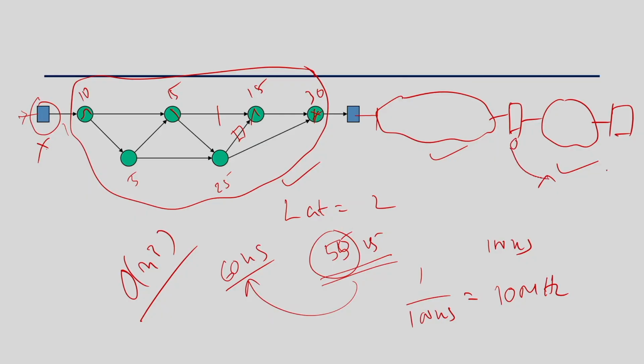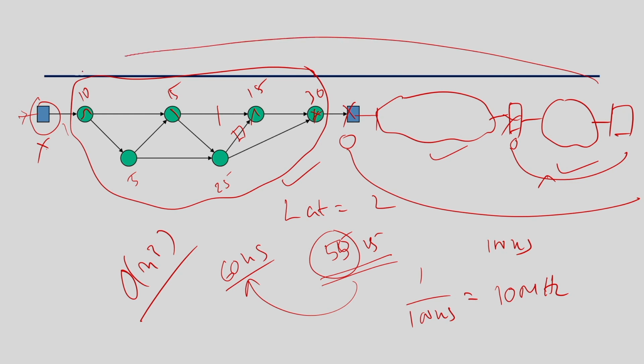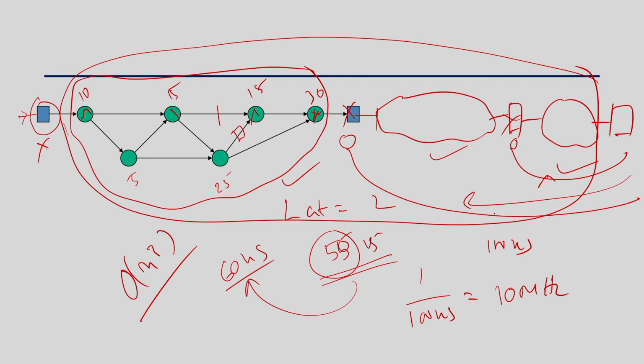I cannot apply it to the complete circuit, but if I apply peripheral retiming, my registers will be moved to the outside. So, basically what I am trying to say is that you move this register here, you move this register here, and this is out there. So, now there is no register here, and this is a complete combinational unit. So, I can apply the optimization to this particular part, right, and I can apply more optimization, because there are more opportunities because of the bigger circuit, and then you move the registers back using the retiming algorithm to the proper place, so that your target clock is met. Okay. So, these are the three kinds of techniques, and these are all done for timing minimization.